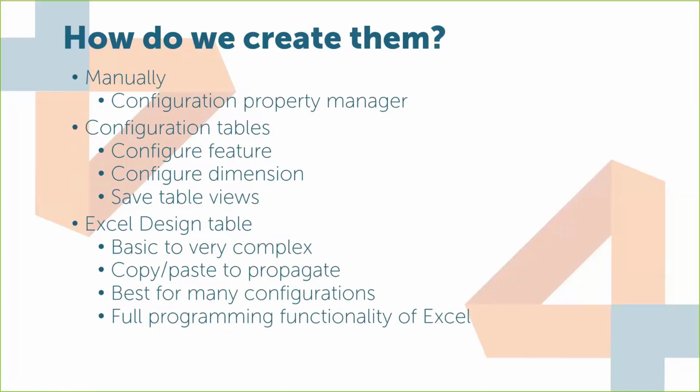They really cover everything from basic configurations to very complex configurations, a couple configurations to hundreds of configurations. The beauty of Excel is all the copy and paste functionality, the programming, the equations. I mean, if you are an Excel guru, it's pretty amazing what one can do with an Excel-based design table. Personally, I keep them simple. I use them for maybe fewer configurations, but I think they work best for multiple configurations because it's a nice, clean table, really makes it easy to understand what's going on and to control, again, a large amount of data.